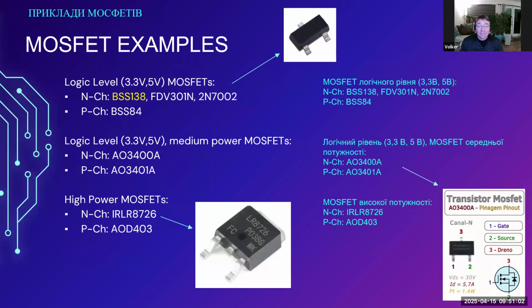These are just ones that you could technically directly connect to an output from a microcontroller because the gate capacitance is very low. It is just a few picofarads, and you don't have to worry about creating a too high of a capacitive load for the MCU output or the logic output.